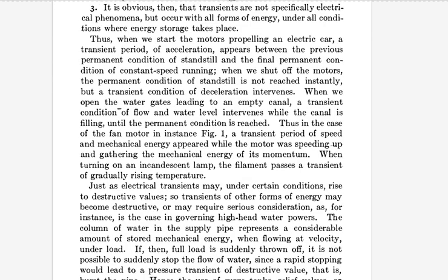3. It is obvious, then, that transients are not specifically electrical phenomena, but occur with all forms of energy, under all conditions where energy storage takes place. Thus, when we start the motors propelling an electric car, a transient period of acceleration appears between the previous permanent condition of standstill and the final permanent condition of constant speed running. When we shut off the motors, the permanent condition of standstill is not reached instantly, but a transient condition of deceleration intervenes. When we open the water gates leading to an empty canal, a transient condition of flow and water level intervenes while the canal is filling, until the permanent condition is reached.